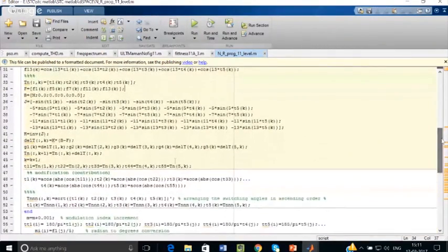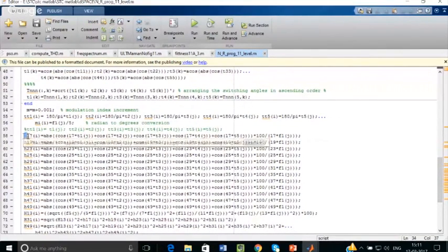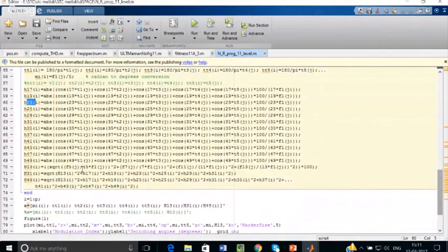And after that, your THD is nothing but the absolute value. Here is the single portion of THD. Here you have the individual harmonics. How will you find the 17th harmonic, the 19th harmonic, the 23rd harmonic? So these are the individual harmonics, and this is your THD. So THD till the 13th.